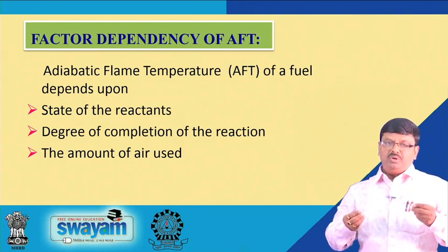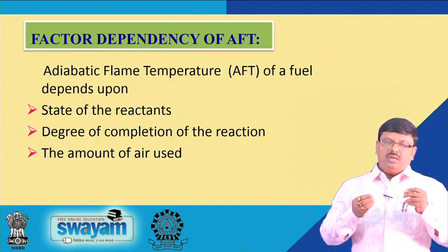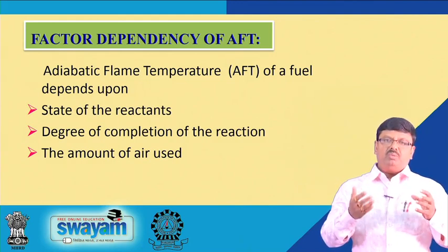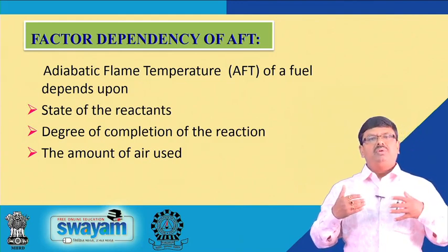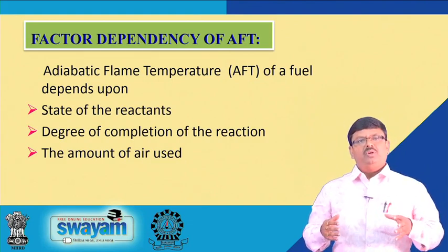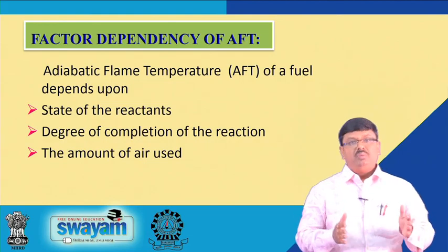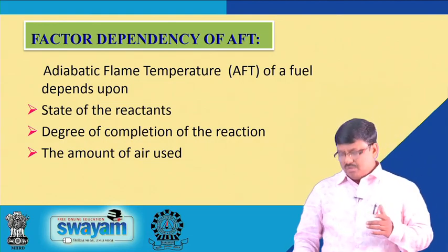This is a very important thing, because to ensure the complete combustion of this combustible fuel, a certain amount of excess air is sometimes required to be supplied to the combustion chamber. So, how much air is to be supplied is also a very important thing to be taken into account.